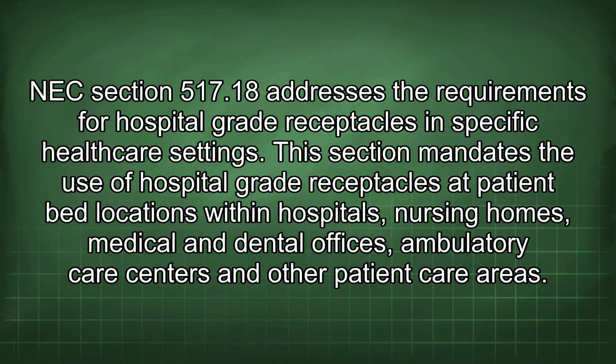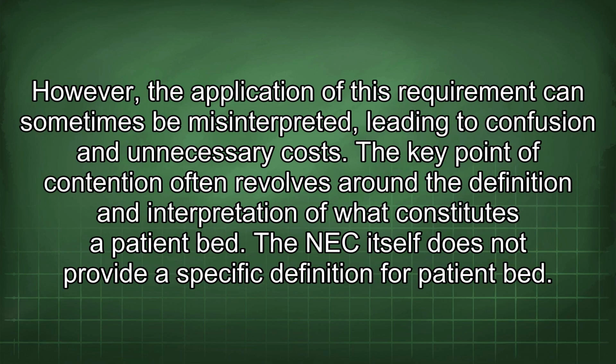NEC section 517.18 addresses the requirements for hospital-grade receptacles in specific healthcare settings. This section mandates the use of hospital-grade receptacles at patient bed locations within hospitals, nursing homes, medical and dental offices, ambulatory care centers, and other patient care areas. However, the application of this requirement can sometimes be misinterpreted, leading to confusion and unnecessary costs.